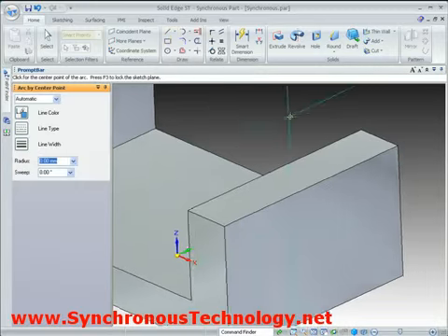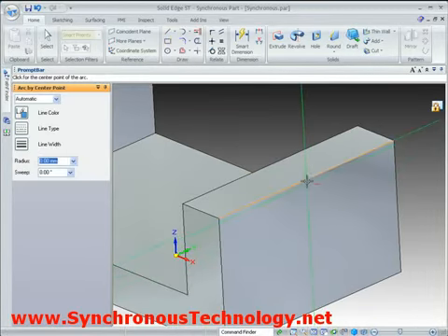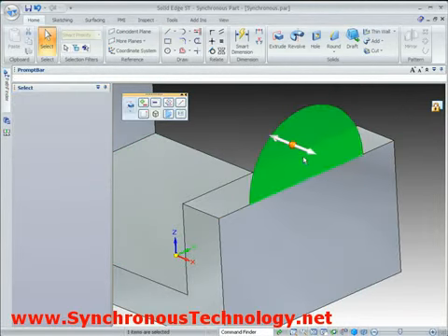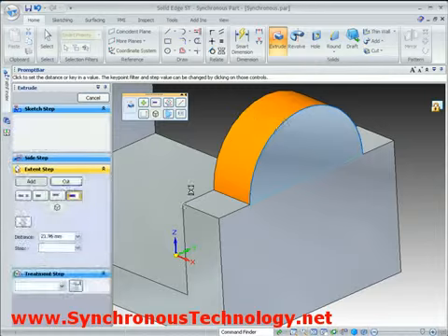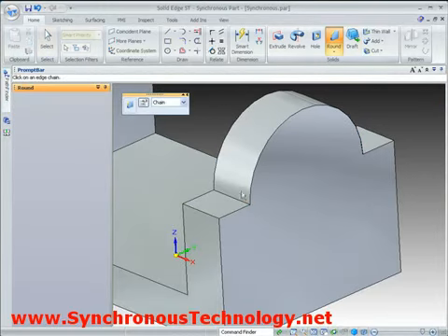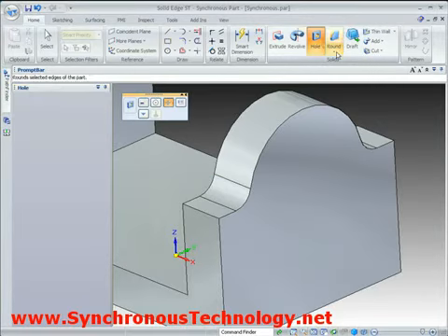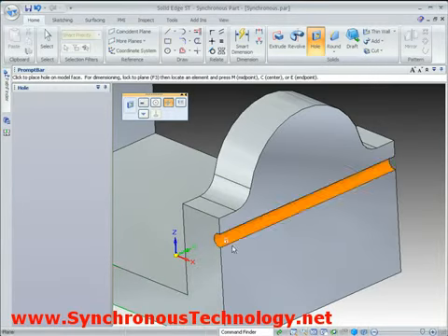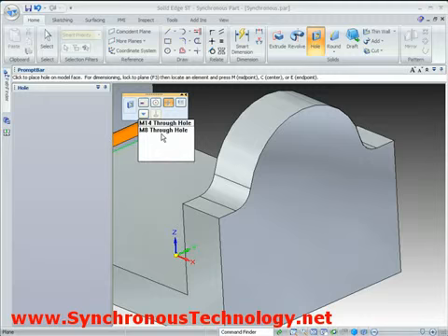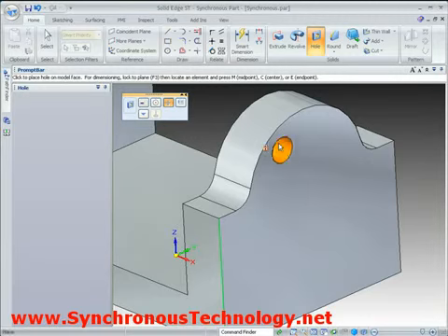Let's carry on and draw an arc on the end face. Then we'll select the region that the arc creates and add the material in the appropriate direction. Then add a couple of rounds to smooth off the corners. When adding holes, the direction of the hole is inferred automatically, simply by dragging across the face. It is also easy to attach them relative to key points on existing geometry.